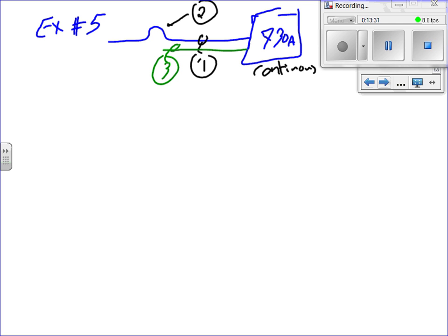The voltage in this, pick and choose. Anything could be 480, 208. Really doesn't matter. Any voltage system. If I get the amps, I don't care, because if I get the amps, I can size the conductors and overcurrent device. I really don't care about the voltage as long as 600 or less, not higher voltage than 600. All right, let's do it. Number 1.